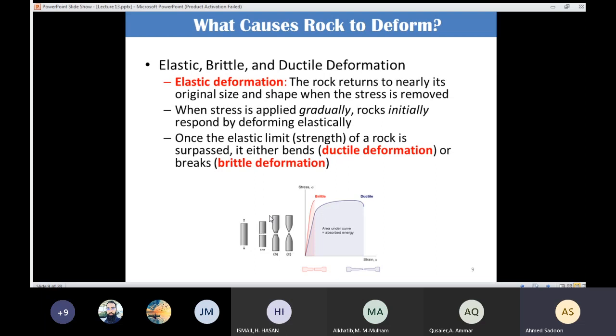In the ductile deformation, like you can see, before the failure or at the place of the maximum capacity for the stress, we are going to have deformation, large deformation actually, compared with the brittle material. Here, before the failure, we are going to have the necking process like this one. If you are going to draw the behavior in terms of stress and strain, you plot it in charts.